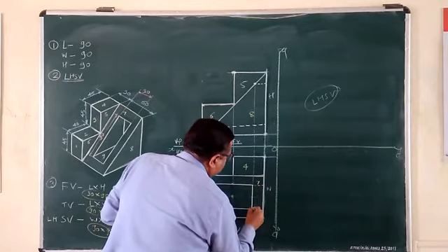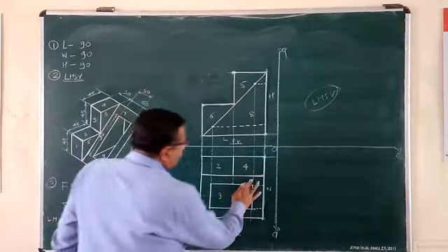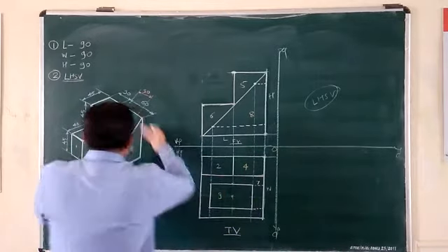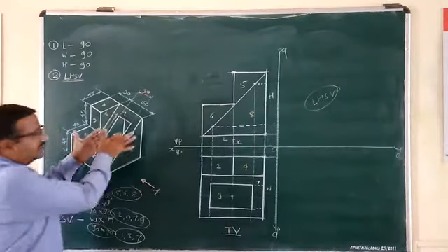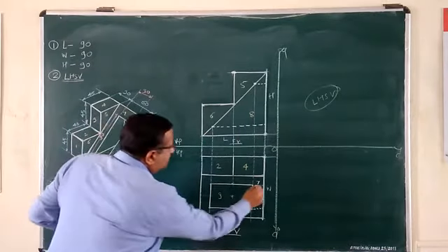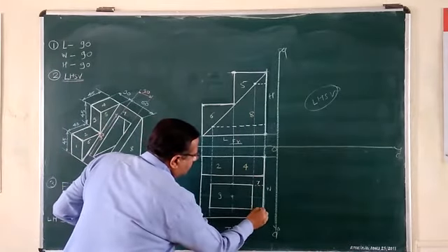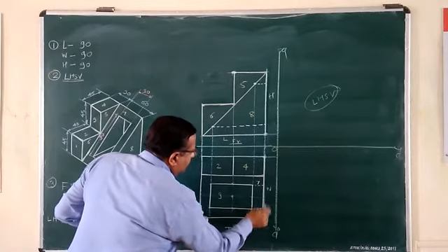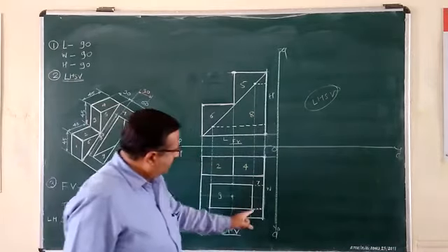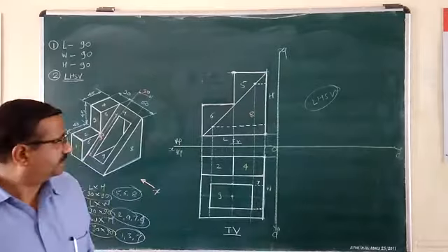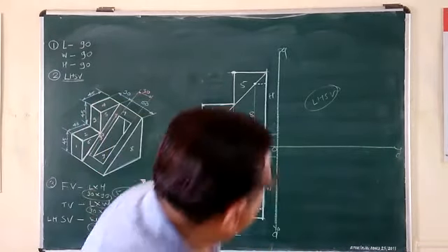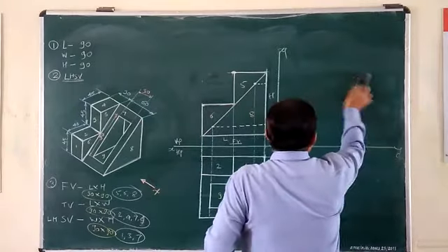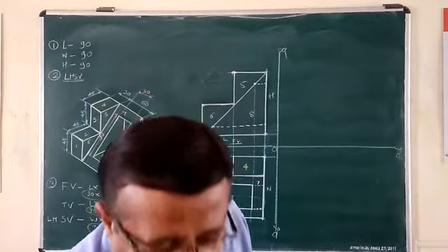In this way. Okay. So here is the right extreme surface. Back surface is here up to that. Because the through hole is cut, corner should be shown till the end of the object. So the object gets ended here. So up to that, those lines should be stretched. Okay. So in this way, front view and top view, both I have shown you. Now ultimately, we will show its left hand side image.